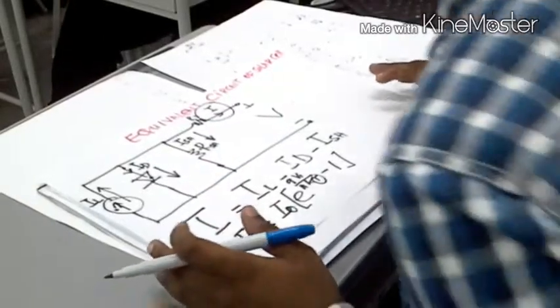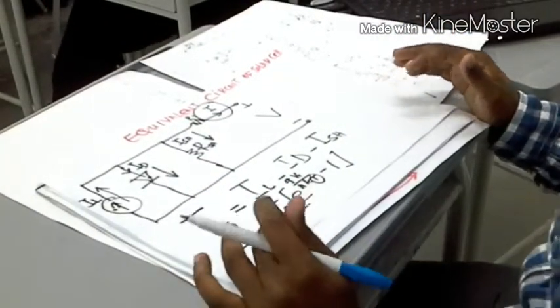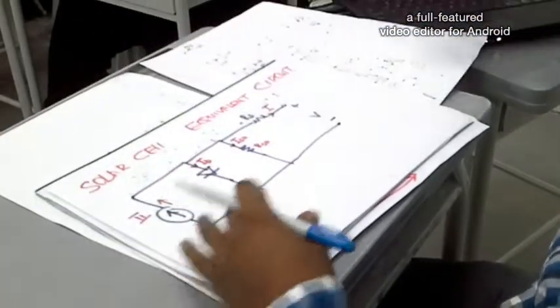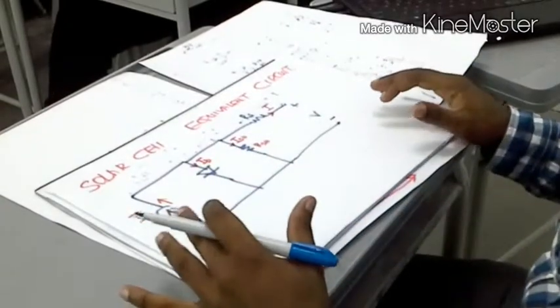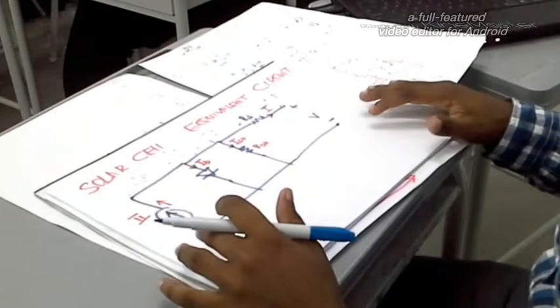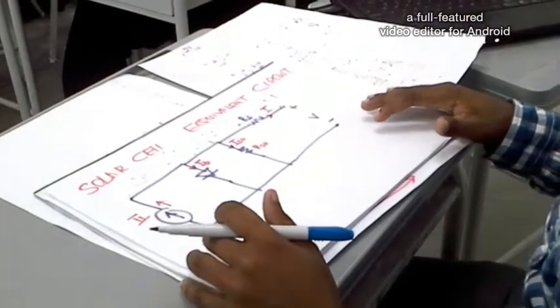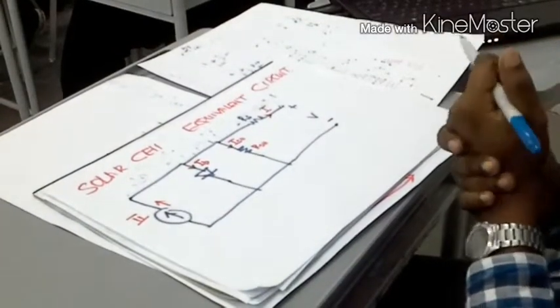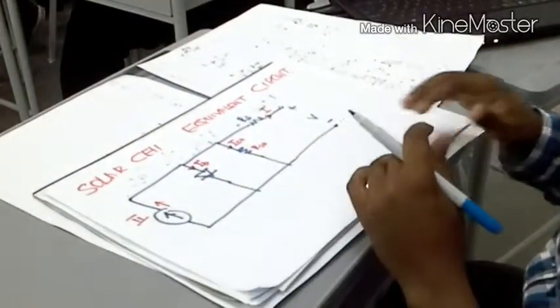Okay, now let's consider the open circuit voltage and short circuit current. If we have this circuit, I just redraw it properly. When the cell is operated at open circuit, the current is equal to 0, and the voltage across the output terminals is defined as the open circuit voltage, assuming the shunt resistance is high enough to neglect the final term of the characteristic equation.